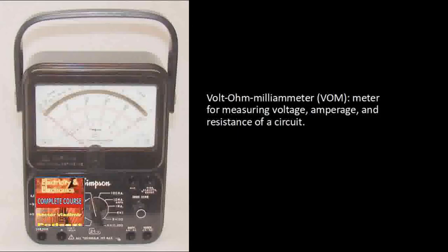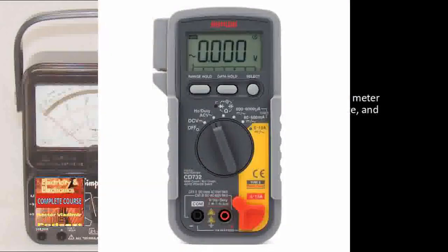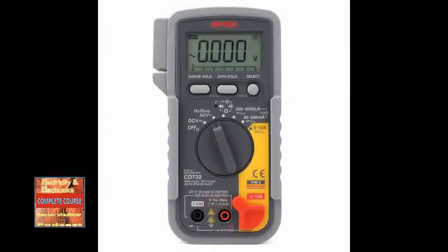On all meter measurements, make a flash check before permanently connecting the meter to the circuit. What does a flash check mean? First, a decision should be made on how to connect the meter to the circuit. Then only the negative lead should be connected, with the positive meter lead left disconnected, while observing the meter. Quickly touch and remove the positive lead to the circuit. Did the needle move in the wrong direction? If so, polarity must be changed.